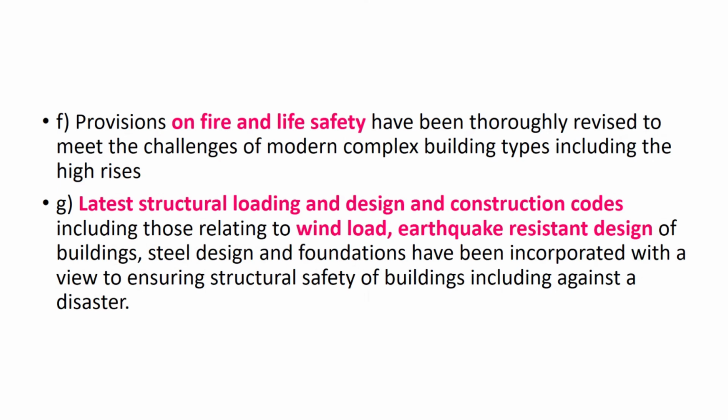So I am reading NBC provision Part 8, Section 2, page 47, building services. Usually, no installation work should start until the building is reasonably weatherproof. But where electrical wiring is to be concealed within the structure, as may be the case with a reinforced concrete building, the necessary conduit and the ducts shall be positioned firmly by tying the conduit to the reinforcement before the concreting. But again, it is silent with respect to the structural integrity. It is trying to tell as to how it is to be done.